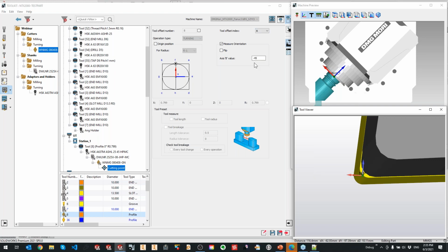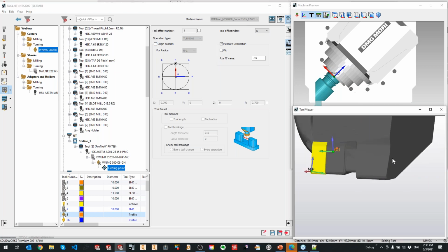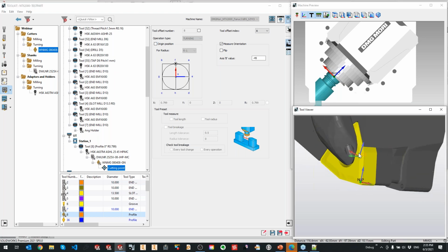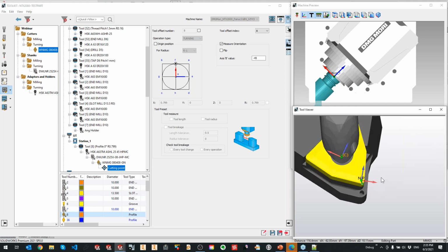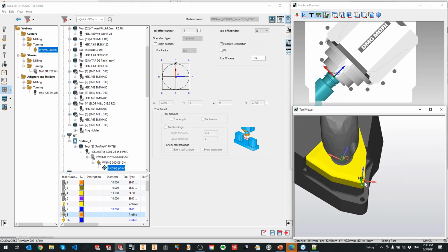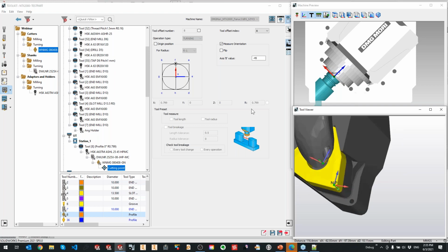Now I like to use this one. Everything is nice, and I want to show you a couple of other options. If you're not satisfied, you need to understand also that because it's STL, SolidCAM actually recognizes more radius origins, let's say so. So it can be this one, it can be that one, it can be another one.